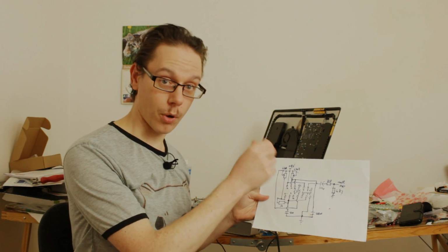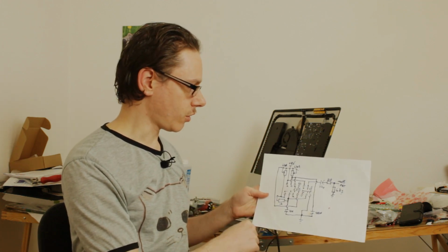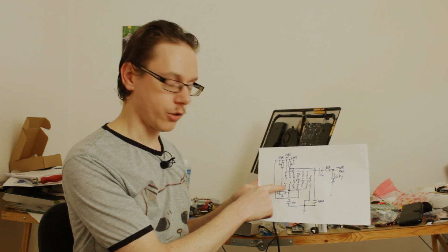But there's one important flaw that you need to notice. When you dial the pot meter all the way to one end, then you run the risk of basically shorting out your power rail. So you've got 9 volts going through the pot meter straight into the chip, and this leg of the chip can actually sink current.